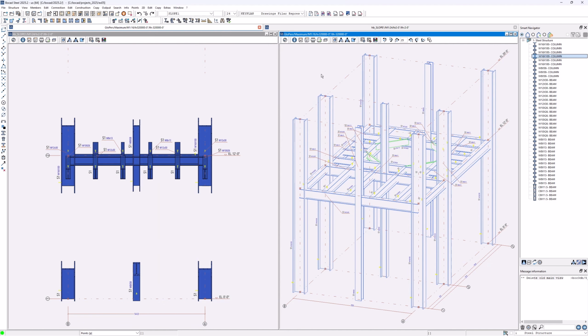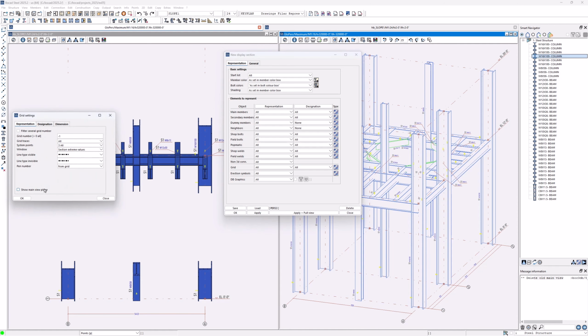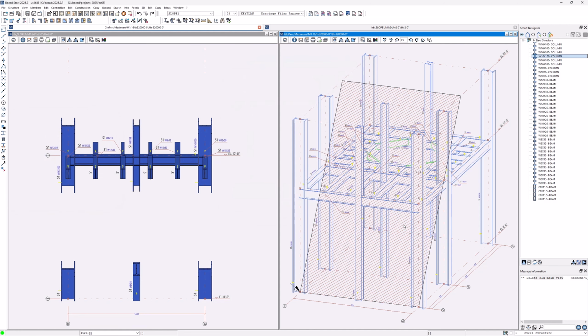through the grid. If we would like to see what this looks like or where we exactly are, we could go to the representation settings, which are here under this icon, and affect the grid, only to quickly switch on a hatching representing where our main view is located. So we can clearly see 1, 2, 3. And this arrow, by the way, indicates in which direction we're viewing.